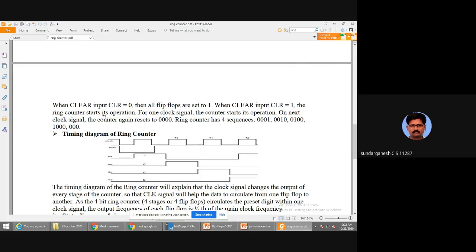So this is the timing diagram of your ring counter. Look at this diagram. This is the clock signal. Initially, 1 is given in the input by the reset signal. It does not normally happen; it is injected into the A flip-flop. Now, during the negative edge of this clock pulse, the signal will start. After this, the signal is not responding, so it is 0 only.